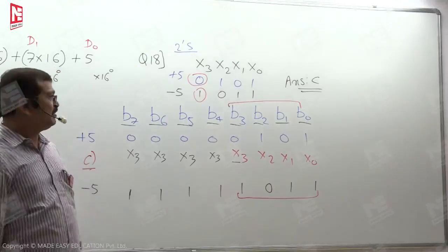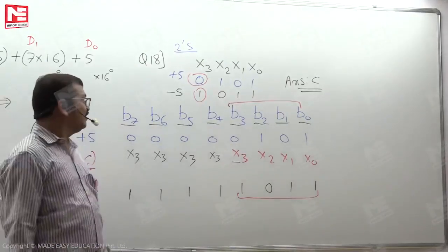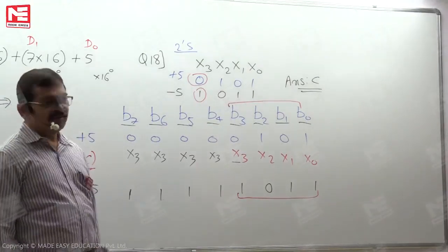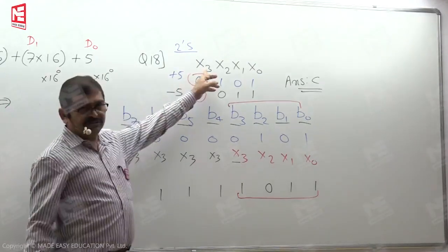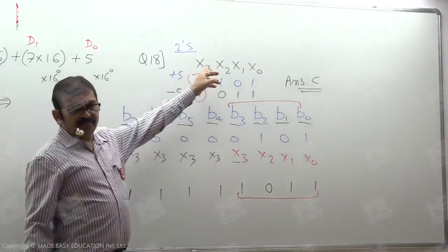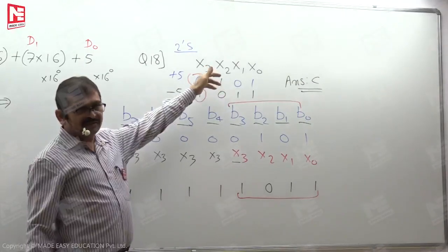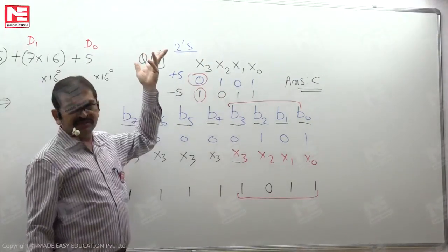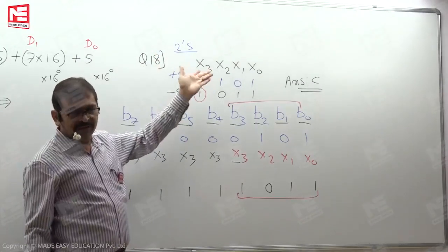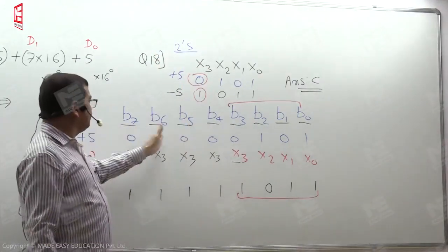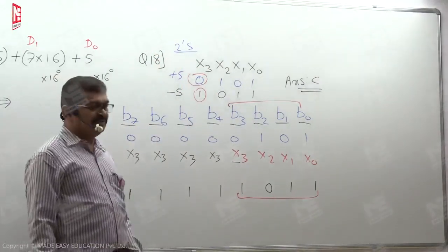With the knowledge of the CO subject, we can say it is a sign extension. In 2's complement numbers, the sign bit is the x3 bit for 4-bit. So when it is copied into a larger size, this sign is to be copied into the remaining bits, the MSB bits. That is the simple way to remember it.